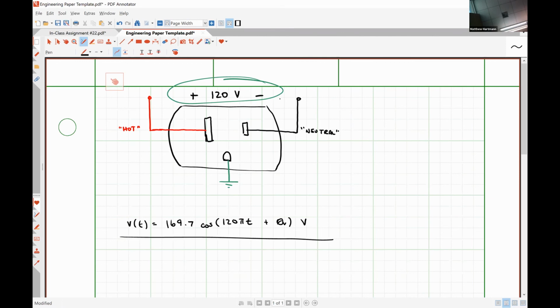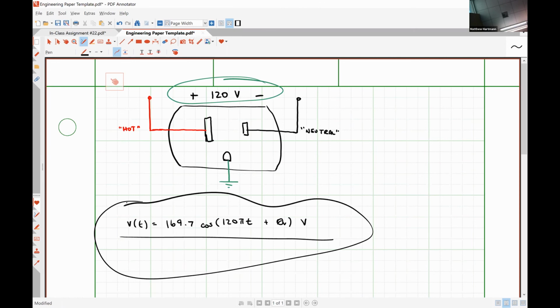So the reason why our complex power relationships, which were developed by electrical engineers in the early 1900s, use effective values is because it would be enormously tedious to have to carry around all of this information for every single calculation. Instead, we use an effective value so that we can do simple DC calculations to determine what size of wire needs to go in your home, which then enables us to calculate proper breaker sizes and all that kind of stuff. So all of the work of an electrician or somebody working in the power industry is based off of these effective values. So that's why we're going to start there before we jump into our complex power relationships. And this is effectively just the first 3 or 4 minutes of that video, so I guess you can skip ahead.